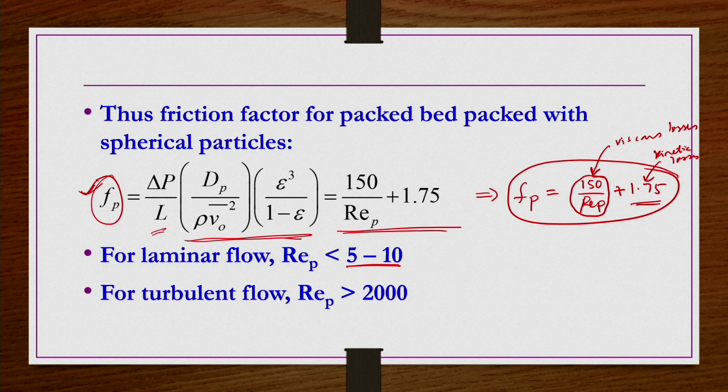Whatever the viscous part contribution is, even if you add it for large Reynolds number, it is going to be a very small value and will not show any influence on the final friction factor value, or on the pressure drop that you calculate.